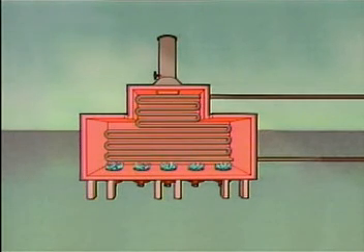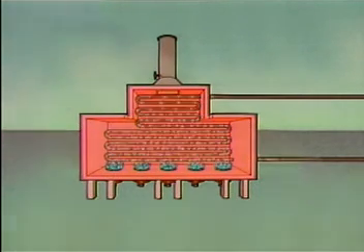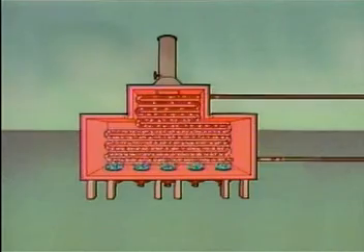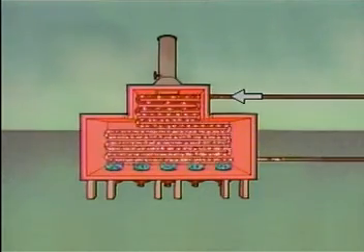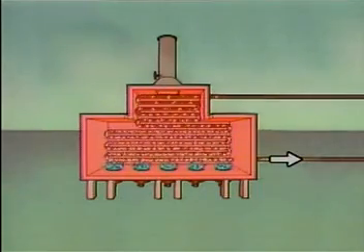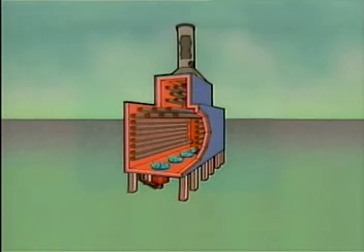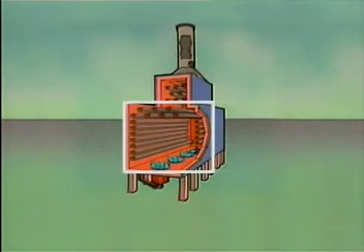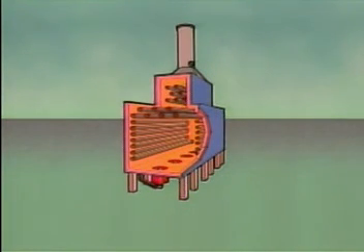In addition to burners, furnaces contain many other important parts. Inside this furnace, tubes carry the process fluid through the furnace. The process fluid enters the furnace in the tubes near the stack, passes through the tubes, and leaves near the bottom of the furnace by the burners. The tubes in this furnace are grouped into two major areas. This area, which is closer to the stack, is called the Convection Section, and this area, which is closer to the burners, is called the Radiant Section.